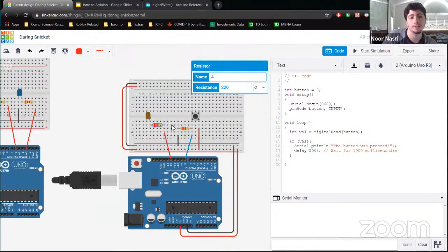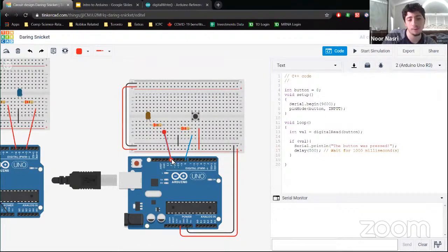We're going to connect it to an LED, 220 ohms. It's going to turn on when 12 is on. I'll put on a PWM just in case they want to play with it later. And then we're going to take it back and ground it. The reason I'm not doing it on the 5 volts is because I don't want it always on. I want it to be on only when this is on. But then it's going to ground in the same place as all of them.